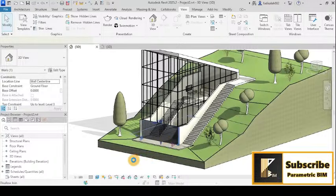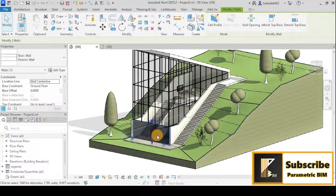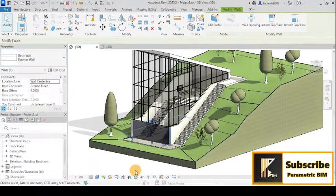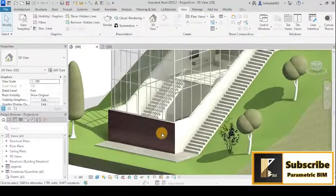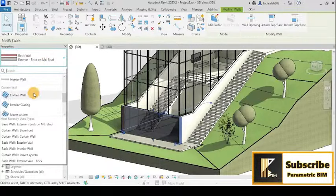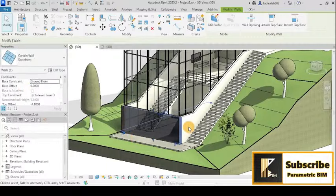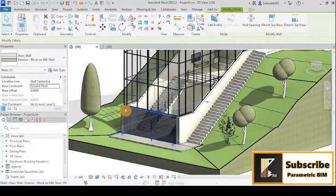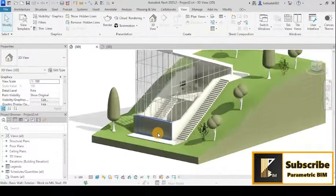you can see that this is the properties of the wall that I have selected. So I can change the type of the wall from here. If I select here, you can see that this wall type has been changed by selecting here from the properties and changing its type from the properties. Maybe you can change it to curtain wall or anything you want. So from here you can control the properties of any component that you have selected.